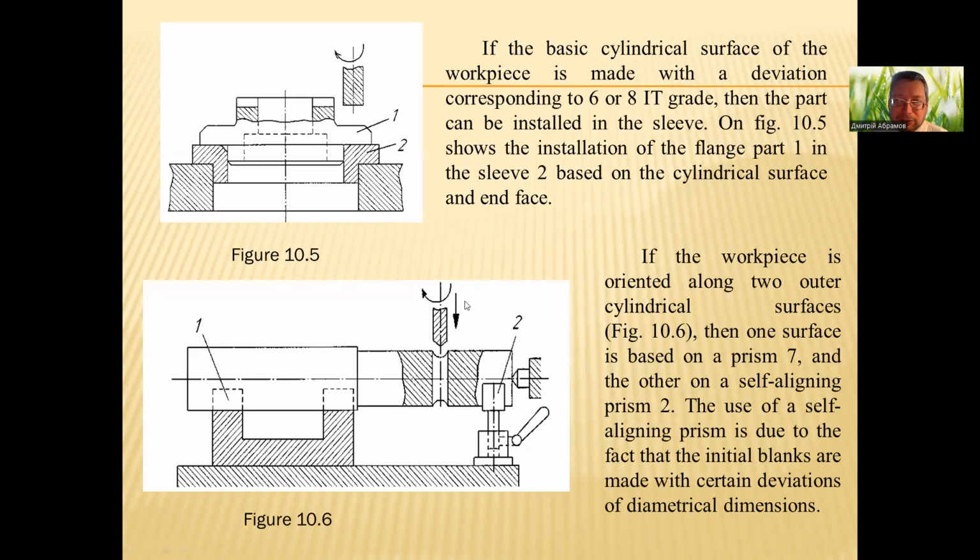If the basic cylindrical surface of the workpiece is made with a deviation corresponding to 6 or 8 IT grade, then the part can be installed in the sleeve.